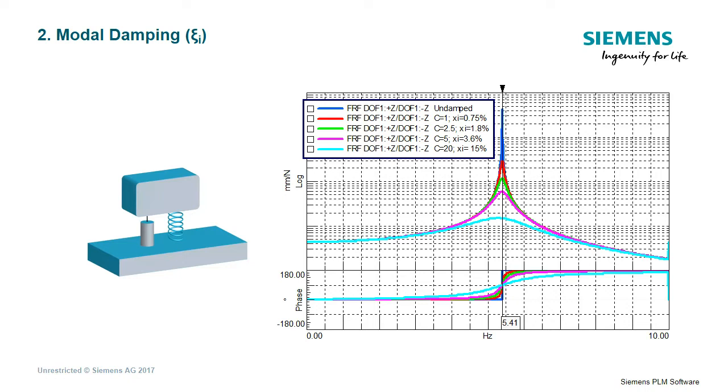Because of damping, the actual damped natural frequency will slightly decrease with increasing damping. However, the undamped natural frequency will remain constant. Damping can thus be seen as a safety factor for vibrations, since it reduces the amplitudes and makes the system response smoother.